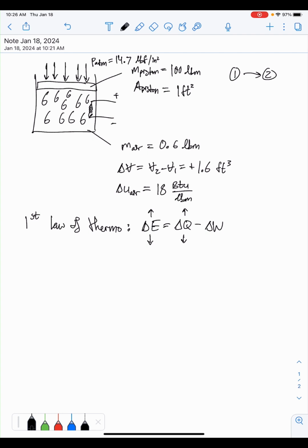But it kind of explains how we define work. What I mean by that is when work is positive, when work's being done, we're actually losing energy because of this minus sign. So that means when work is being done by the system, for example, expanding a piston, you're giving off energy into the environment. So that's positive work. Your system is doing work, but that results in decreased energy.